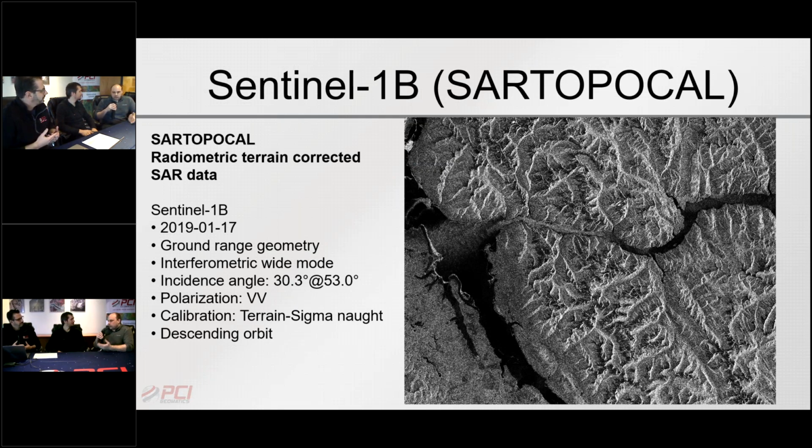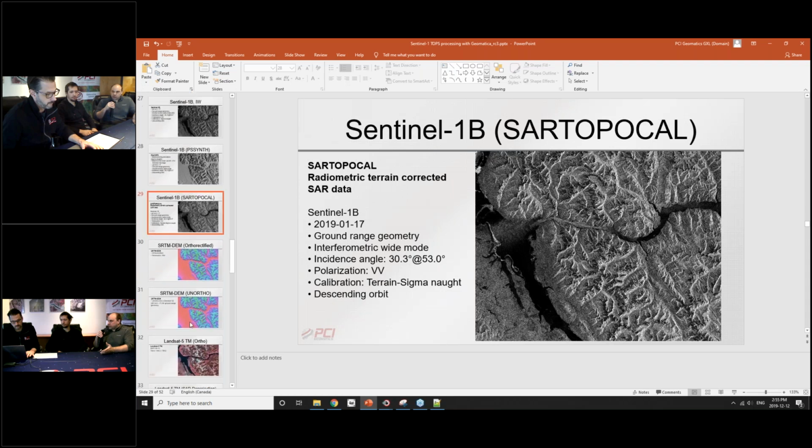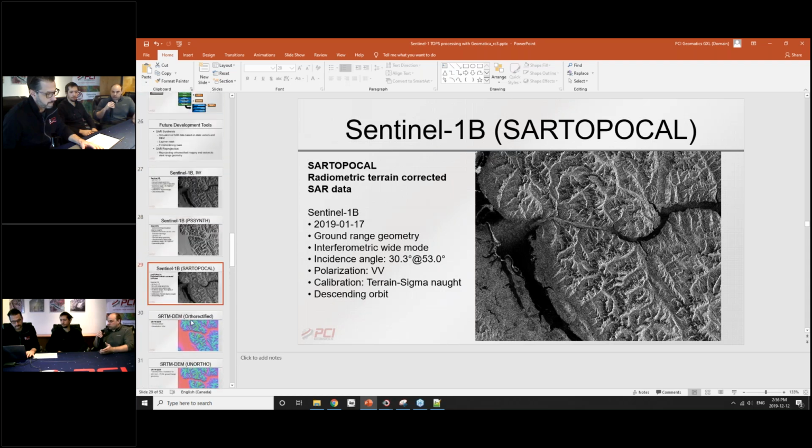And when we talk about the integration, the second part, the calibration is really the first part. But since now we know pretty well the geometry of acquisition, that means we are able to take any other piece of ancillary information that is already ortho-rectified. This can be a Landsat image, a DEM, a Sentinel-2 image, or we can take any ground truth points and reproject them onto the slant range geometry of the SAR image, if need be.